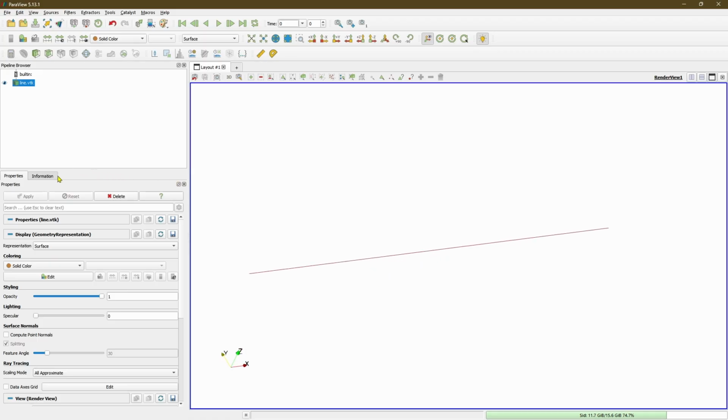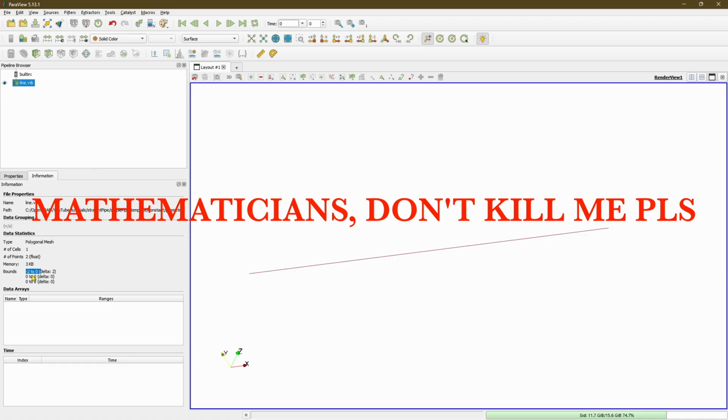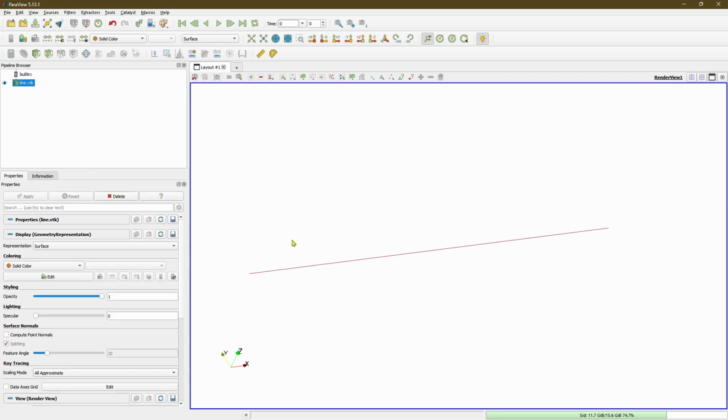So this line object that I have has units of -2 to 0. Sorry, rather -2 to 0. There's no positive there. This represents the skeletal structure of the pipe object that we are trying to make for our mesh. Essentially, we will take a circle and extrude it along this line using blockMesh as we did previously. This is useful for that particular purpose. Let's go back to it once we discuss the blockMeshDict file.